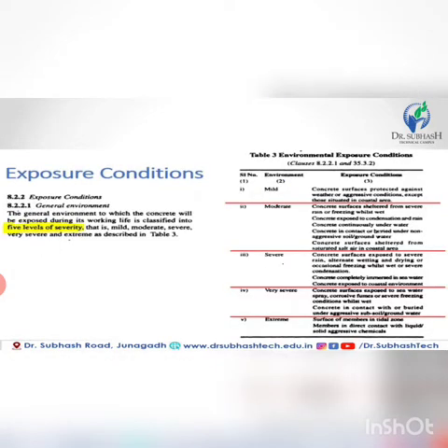Next, exposure condition. The general environment to which concrete will be exposed during its working life is classified into 5 levels of severity: mild, moderate, severe, very severe, extreme.